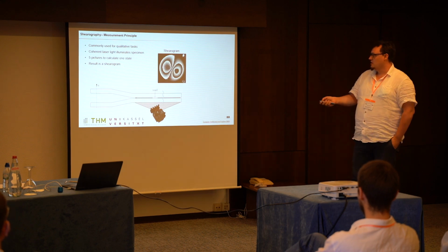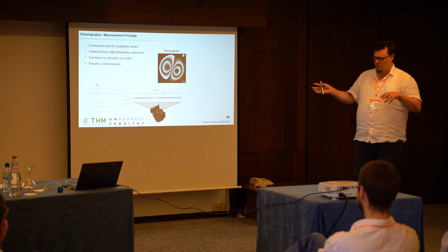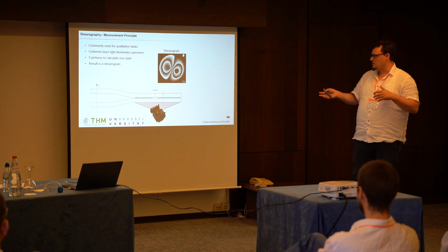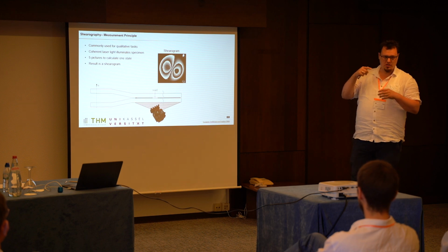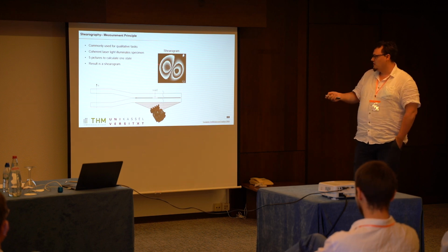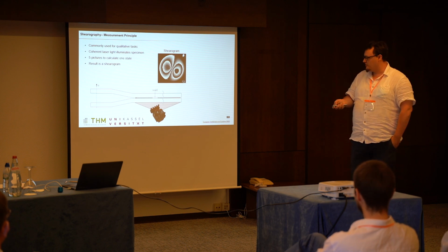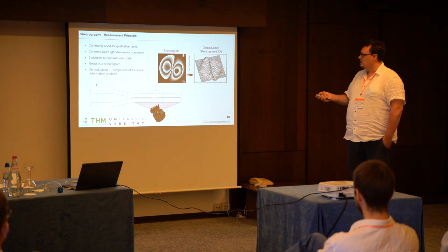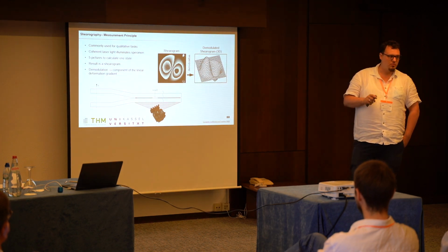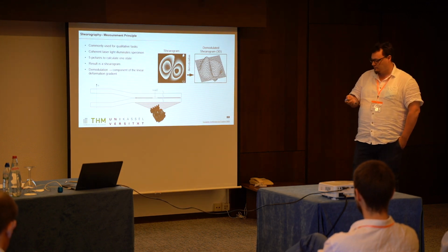You see a picture here, an example, with some phase shifts. This is an example for a circular plate loaded in the middle. Then we can demodulate these pictures. We reduce the phase shift, and this leads to this surface, and this delivers us a component of the linearized deformation gradient.